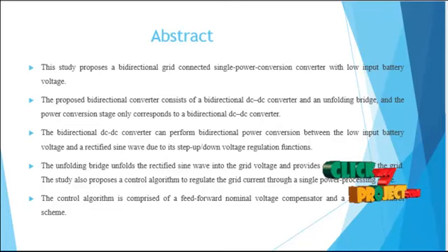However, the two-stage converter involves a bulky DC link capacitor, high switching losses, several semiconductor devices and gate drive circuits. Additionally, the efficiency of a two-stage converter corresponds to the multiplication of the efficiency of each stage. Thus, in order to achieve high overall efficiency, two separate controllers are required, one for each stage. Thus, the conventional two-stage bidirectional converter involves circuit complexity, high cost and limited power conversion efficiency.